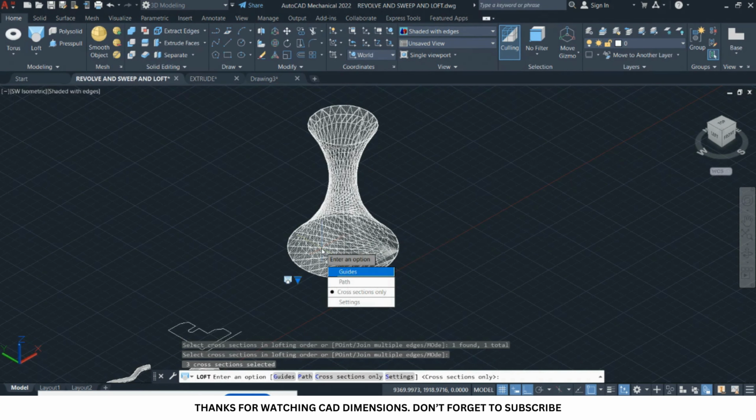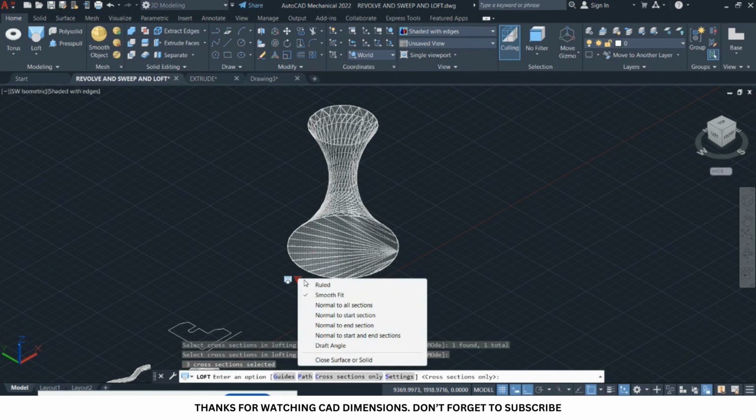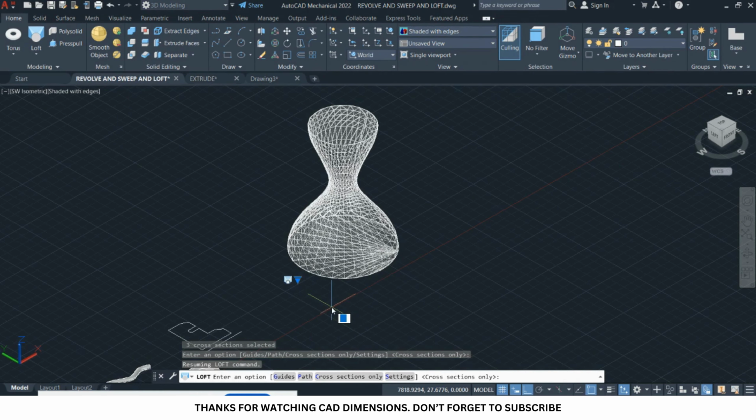So I press enter. Now if I press enter, there are other things that I can do with respect to the loft. If I click on the drop down arrow, for example, I have normal to all section. Click on that and see how it behaves. This is the normal to all section, that is, the loft is normal at each of the shapes that you've drawn.